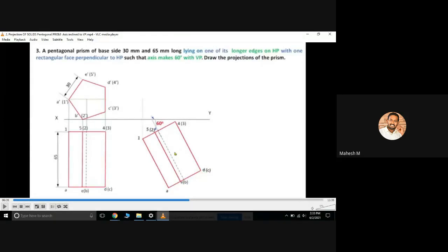Now we are going to make the second front view. It is an inclined front view. You can project the 5 points from our previous front view. Each and every point will have a horizontal line and a vertical line. Please remember that it is common for all the problems. So if you are projecting A of 1, you can connect this A of 1 horizontal line with the vertical line. This intersection will be marked as 1 dash, sorry, 1 1 dash.